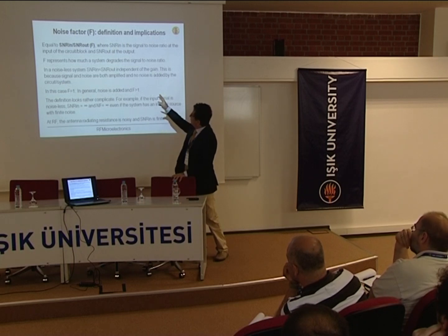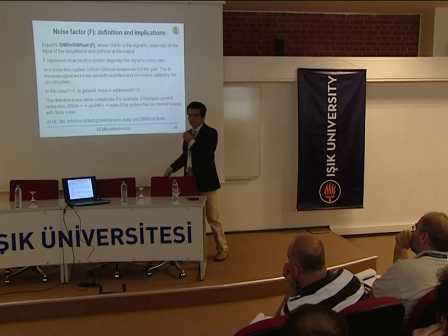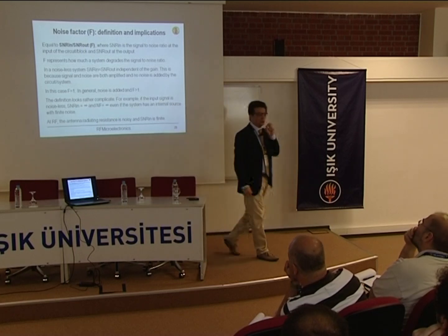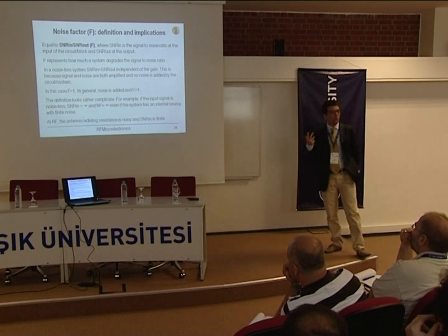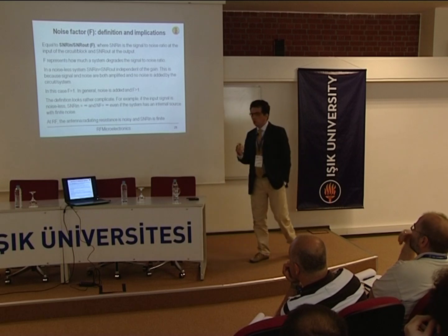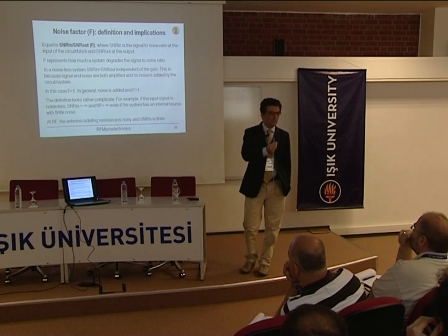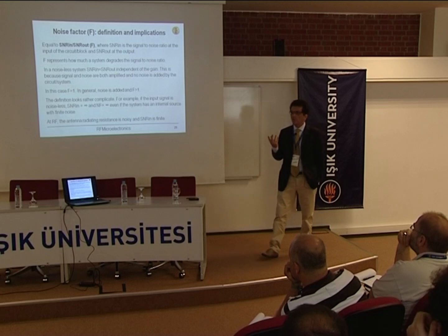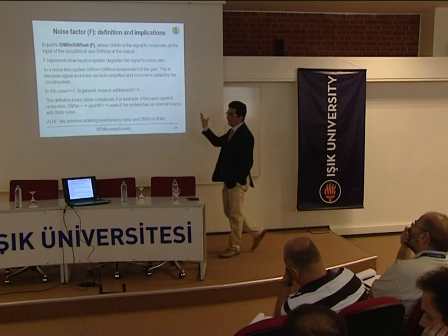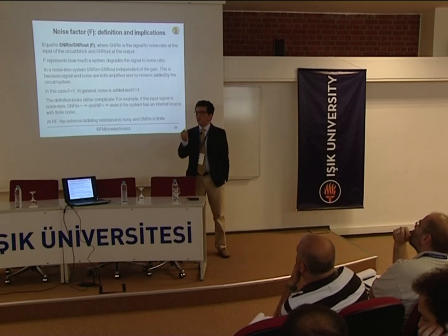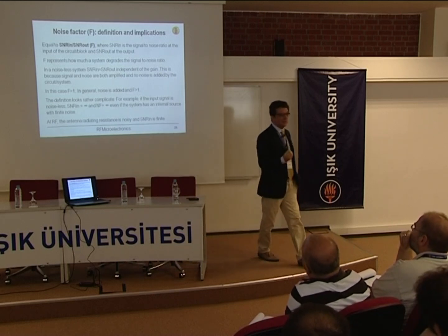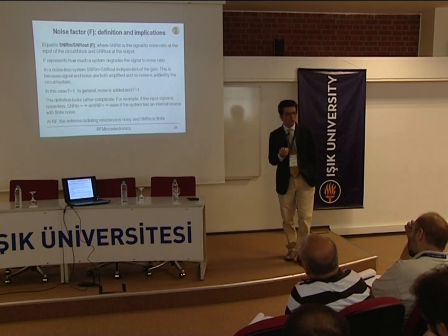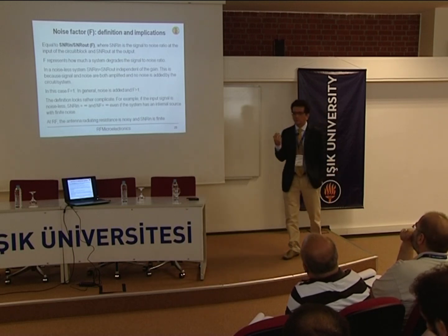So, of course, due to the definition, you can conclude that if the circuit is not contributing any noise because it's an ideal noiseless circuit, then the input and output signal to noise ratio are equal, and then the noise factor would be equal to 1. So noise factor equal to 1, or 0 dB in decibels, is the minimum theoretical noise factor or noise figure that we can find.